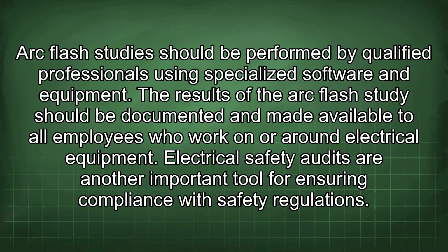Arc flash studies should be performed by qualified professionals using specialized software and equipment. The results of the arc flash study should be documented and made available to all employees who work on or around electrical equipment. Electrical safety audits are another important tool for ensuring compliance with safety regulations.